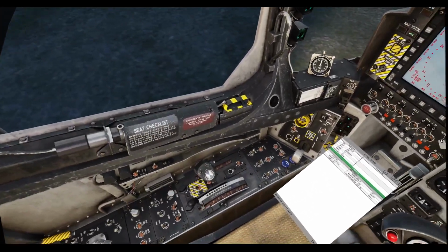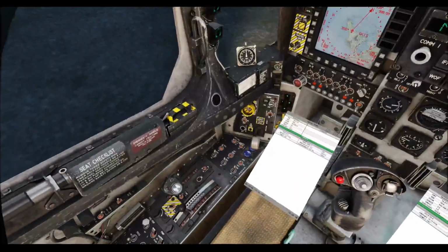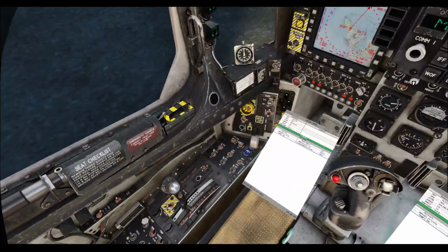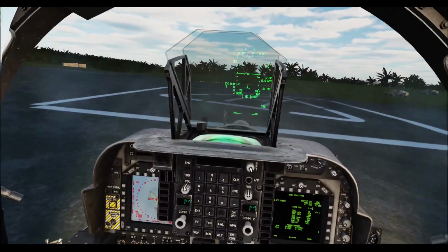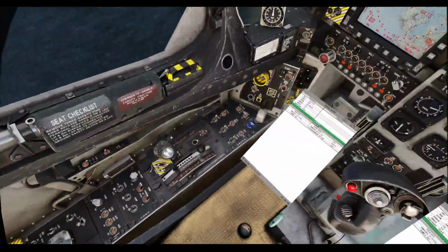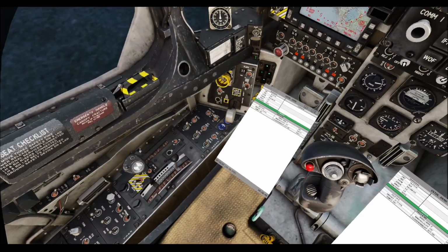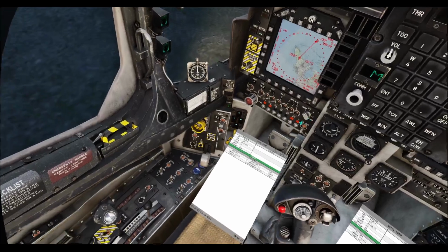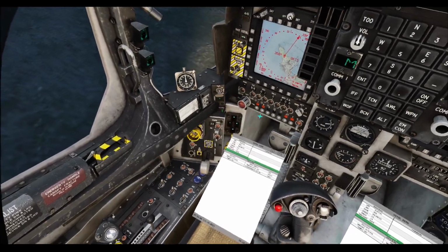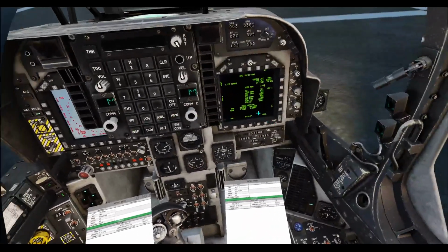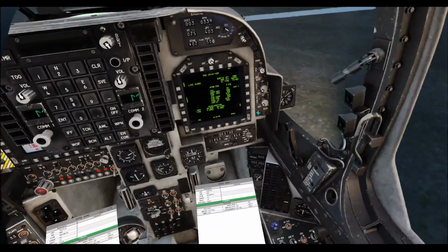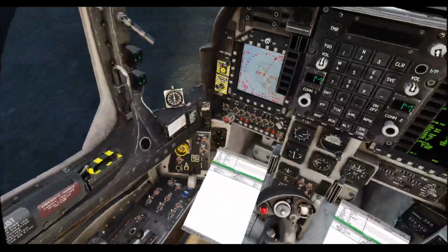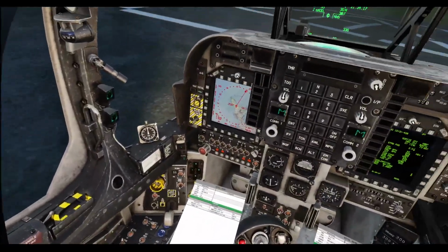One finger checks, I'm going to put the stow stop to 70 there. And I'm going to check that the nozzles are set to 70. Then I'm going to set the nozzles to 30. Perfect. Coming forward, I'm going to make sure that the nose wheel steering is in the anti-skid position. My flaps are in the STOVL position. Combat water's on. Takeoff water's on. And then I'm going to make sure that I'm trimmed to 2 degrees nose down, which I am. And that should be everything for the one finger check.